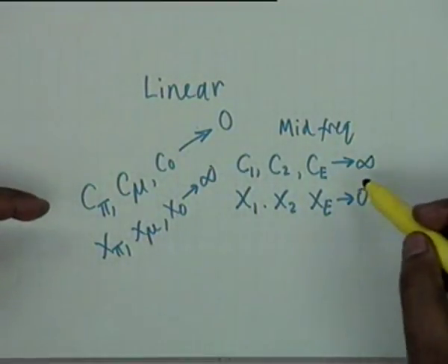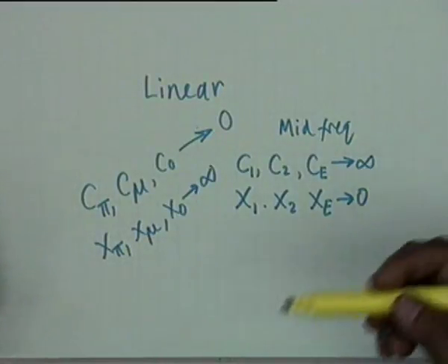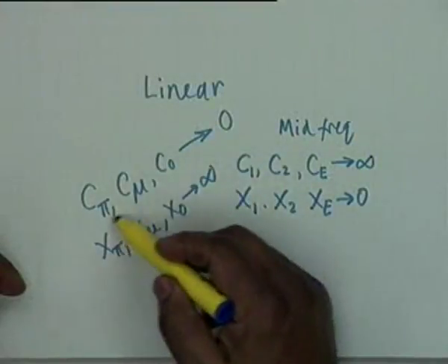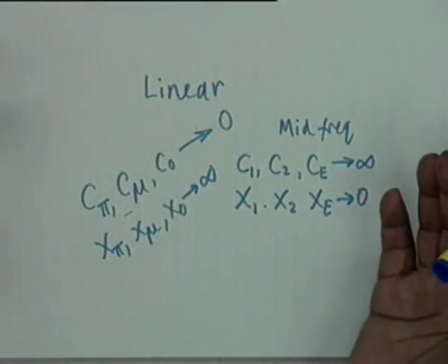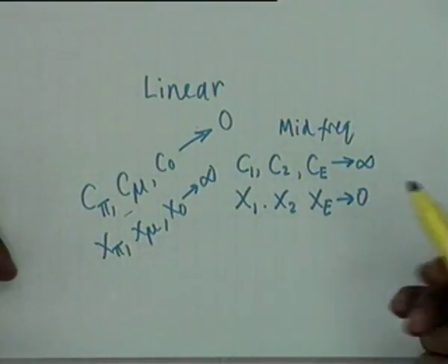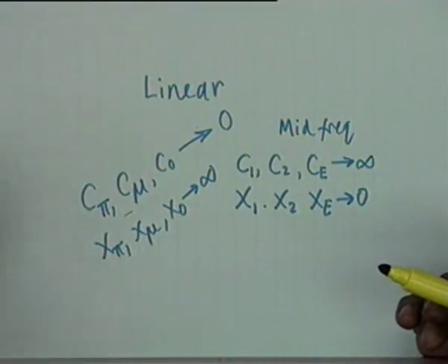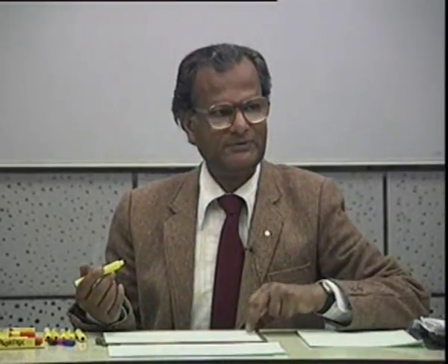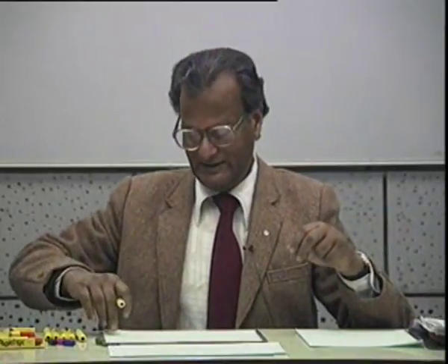Okay, the 2 sets of capacitances are ignored due to 2 different reasons. One is these are very small and therefore their reactances are very large, they are open. These are very large, therefore their reactances can be considered as short. Okay, if that is so, then at mid frequency we can only work with resistive equivalent circuit. Okay, nothing else.